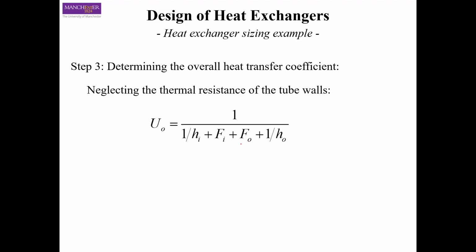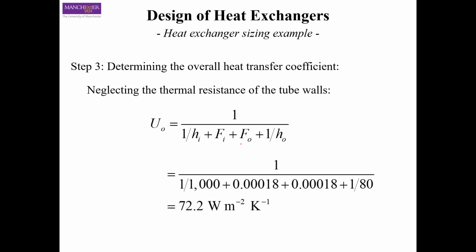Because we know the value of all these parameters, we know the value of h and the fouling factor for inside and outside of the tube. So if you just plug in the values, you know the overall actual heat transfer coefficient.